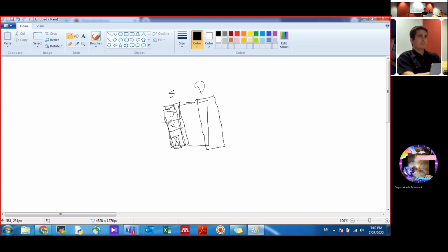Not connecting all of them through the transistor. I just use the wire at the side. This is one way to do it. And you do it over this transistor, the drain here. But the effect is not on the spacing, it is mostly on maybe parasitics between the metals.